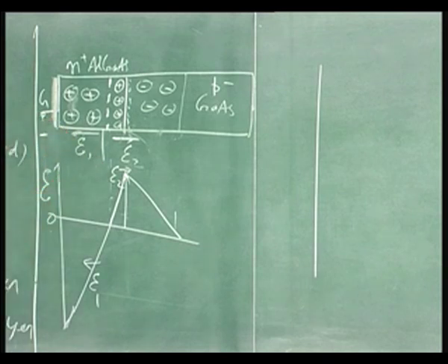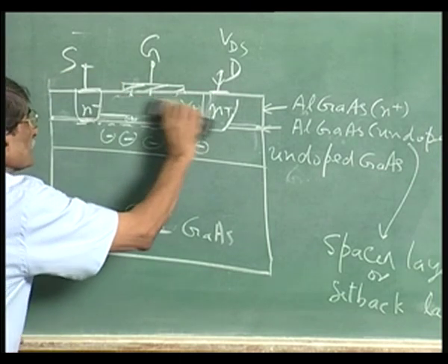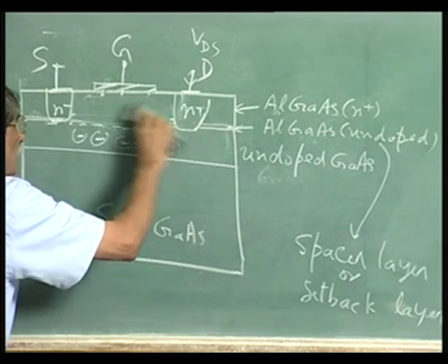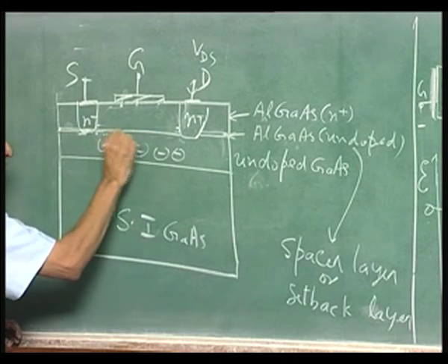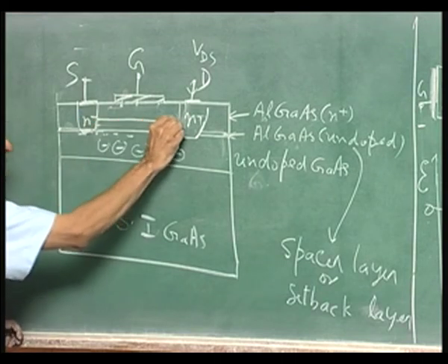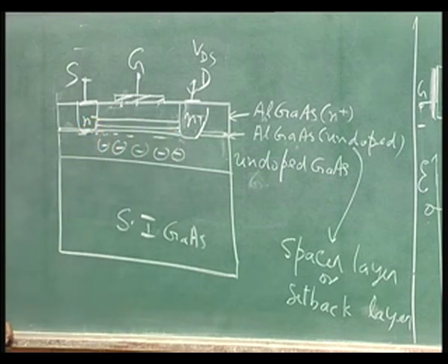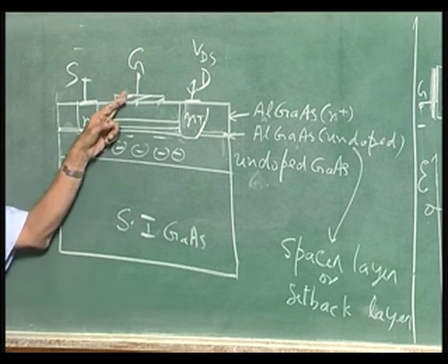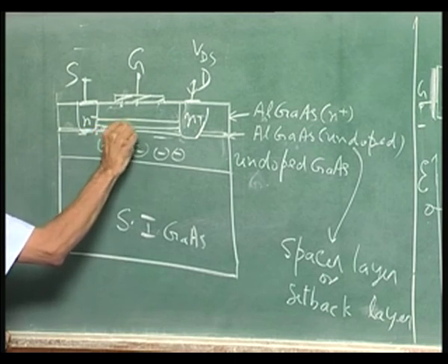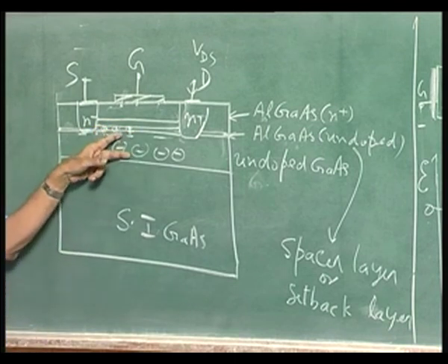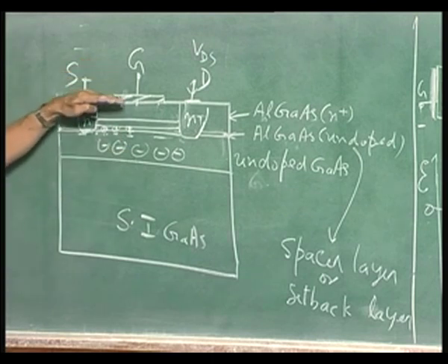It is better to see in this diagram. Till the depletion layer reaches here, for example, when it is here like this, I have the charges, when the depletion layer is up to that point and the depletion layer here is like this. See, as I keep on increasing negatively VGS, this particular thing is already there, correct, because of heterojunction. What I am doing is I am applying voltage between these two, negative. As I keep on increasing, what happens? Depletion layer keeps on widening.